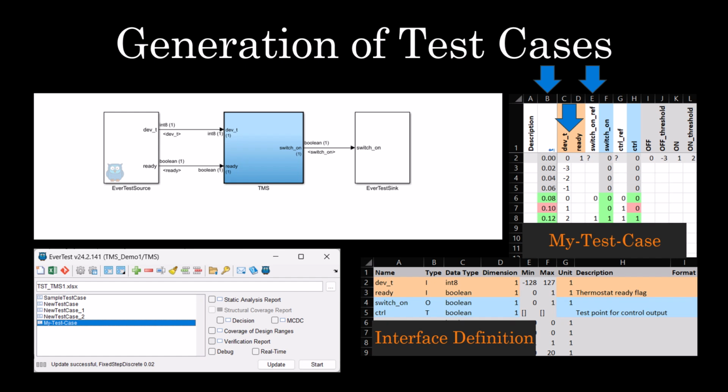Similar to input values, the cells can be left blank if the value does not change during a specific time step. Output values can also be ignored by using the question mark. Output signals will be filled with the actual outputs from the last test run. They will be colored in red if they deviate from the related reference value. They get the green color if they are as expected. The time vector inherits the colors based on criticality, red over green.